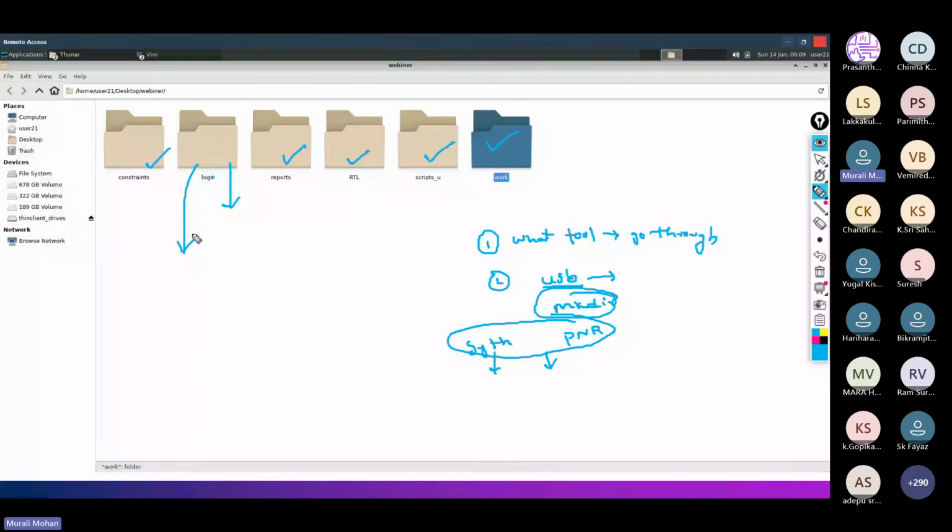particular log file. From this log file, they analyze where exactly the error is coming from, and what you have already tried. Based on that error, they are going to guide you. In the industry, they won't fix it for you, and they won't have enough time to sit with you again whenever you are running that particular stage. So you just share this documentation, that is, the log file. This is the importance of creating the directories for synthesis. I hope it is clear for all.